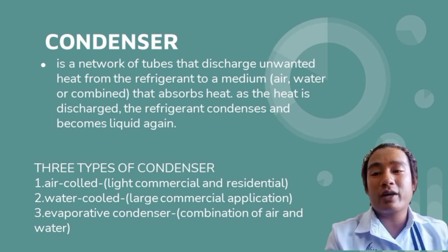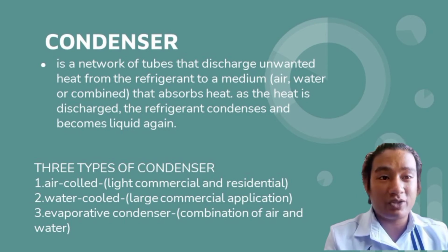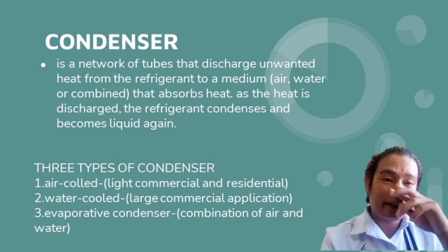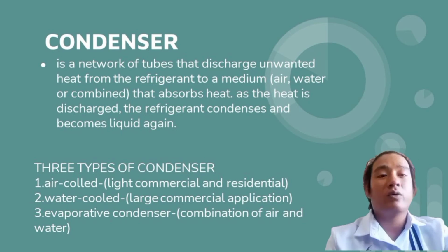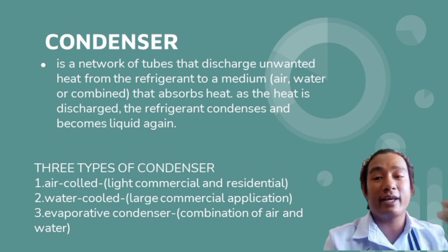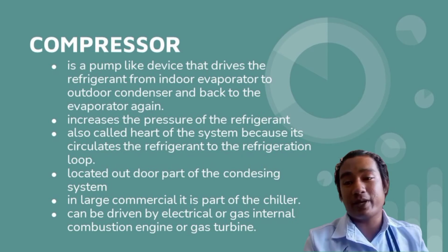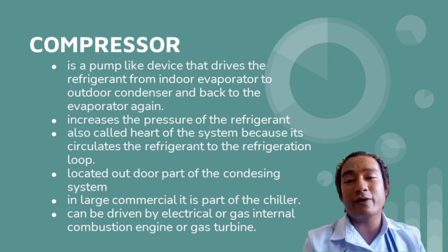The air-cooled is typically used in residential applications. The water-cooled is usually used in large applications such as malls, while the evaporative condenser uses both water and air in its application. Next is the compressor. It is a pump-like device that drives the refrigerant from the indoor evaporator to the outdoor